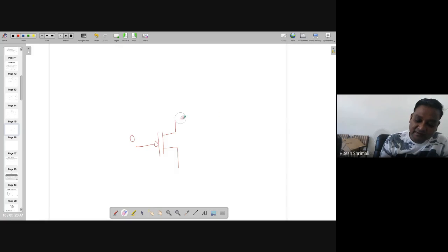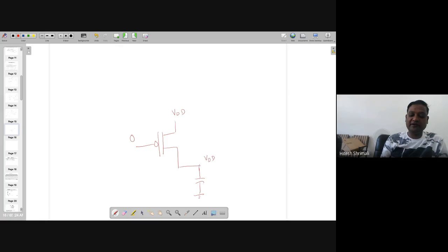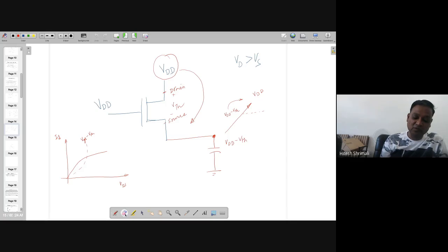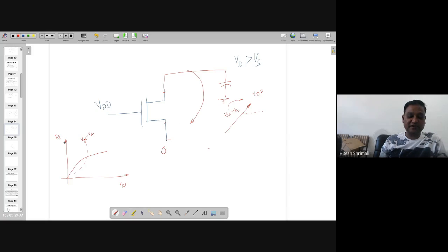But if I connect here VDD, I can transfer the whole VDD over here. You can think about it maybe, and you'll find out that even if it's VDD going here, there is no drop first of all. And this transistor will not be going into the turn off condition. And the same thing will occur over here when we make it in a reverse way. If this is 0, and if I want to transfer 0, then there is no drop. This is happening with the fact that it's following the current equation, right?